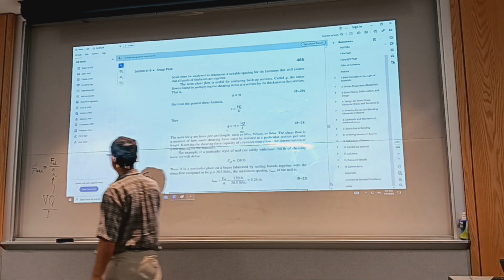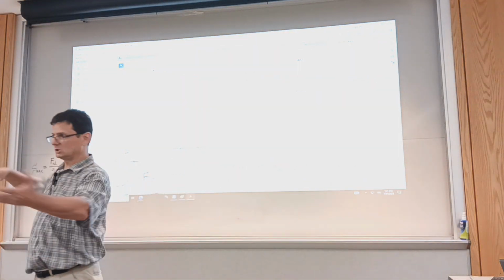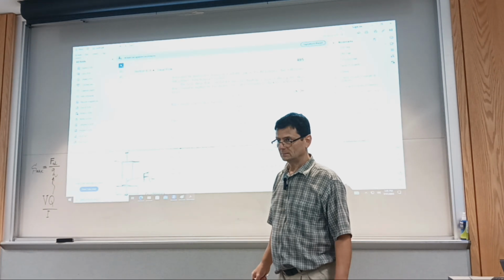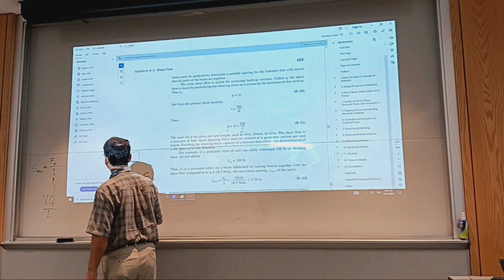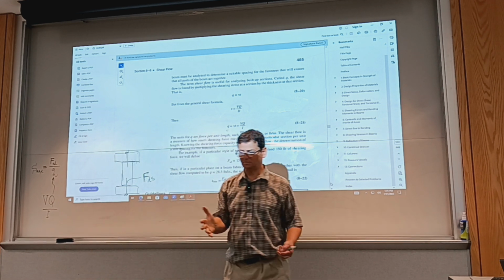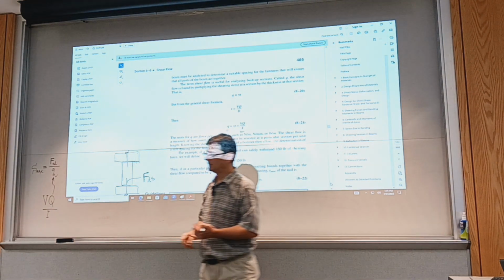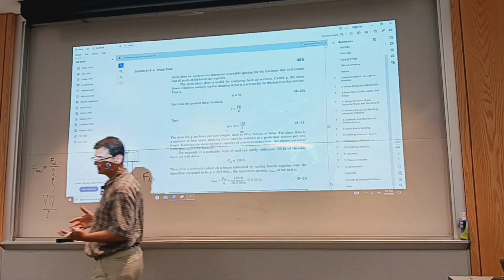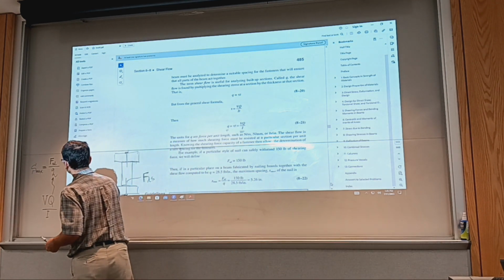Okay, I can calculate at what distance I need to apply nails to fabricate that I-beam using 2x4s, or I can do a T. With an I-beam, like our problem with the rivets, it's easier because the centroid is readily available, and the total area moment of inertia is likewise easy to calculate, you don't need the full table. Okay, but yeah, this is what we need.